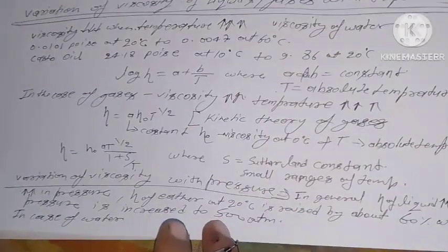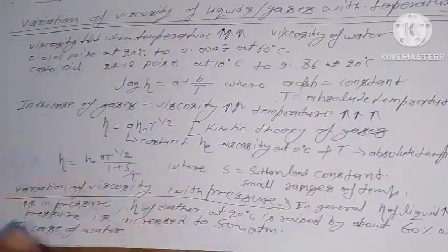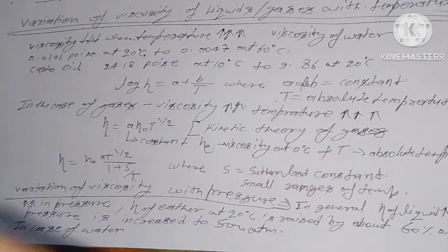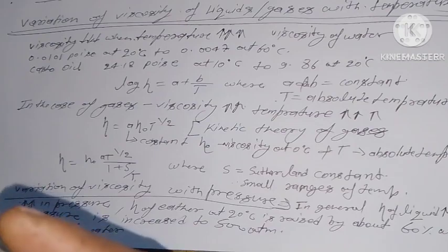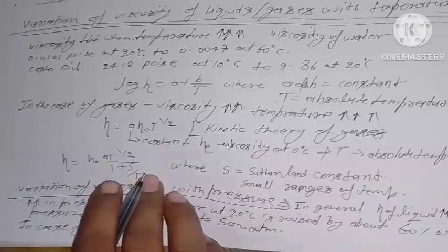For more viscous liquids, the increase in viscosity with pressure is much more than in the case of fairly mobile liquids. For moderate pressure, the viscosity of a gas is found to be independent of pressure, but at very high pressure, the viscosity increases with increase in pressure.